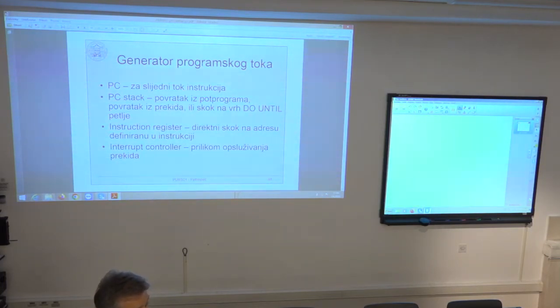in this type of application, usually the useful things are done in only a few assembly instructions. For example, computation of FIR filter 1 step, or maybe computation of this so-called butterfly in fast Fourier transform implementation. It takes 2 values, multiplied by some coefficient, gets another 2 values as a result. So all of these operations are done in only few assembly instructions.